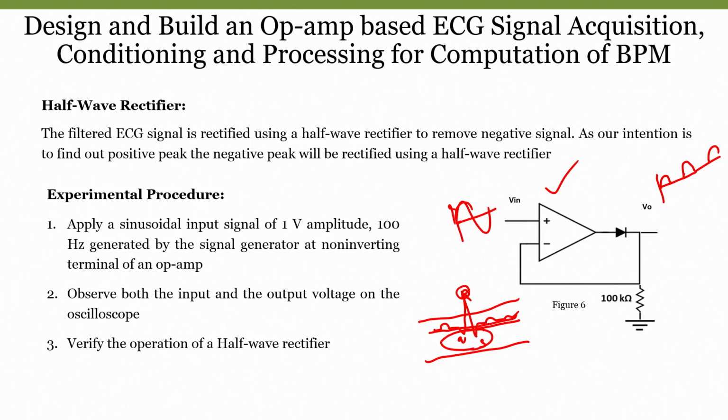But why do we have to consider this? The reason is, when we see the peak, this also will be considered as a peak, this also is considered as a peak. So, if I do not consider the threshold, even these can be considered as peaks, and it is very hard to understand the BPM correctly and accurately. That is the reason, as we already know that the QRS peaks have a very high amplitude compared to other peaks.